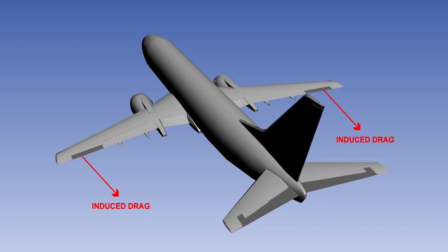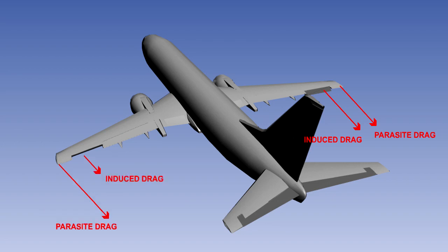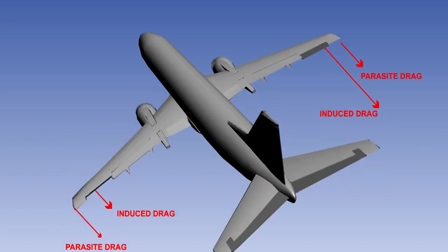There are three main methods in common use to counteract this adverse yaw. They are differential ailerons, Frise ailerons, and aileron rudder coupling. We will now have a look at each of these methods. With differential ailerons, the aileron linkage causes the upgoing aileron to move through a larger angle of deflection than the downgoing aileron. This increases the parasite drag on the upgoing aileron and reduces it on the downgoing aileron, thus reducing the difference in total drag between the two wings.